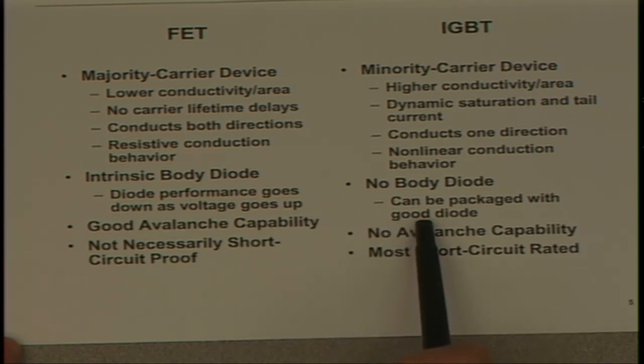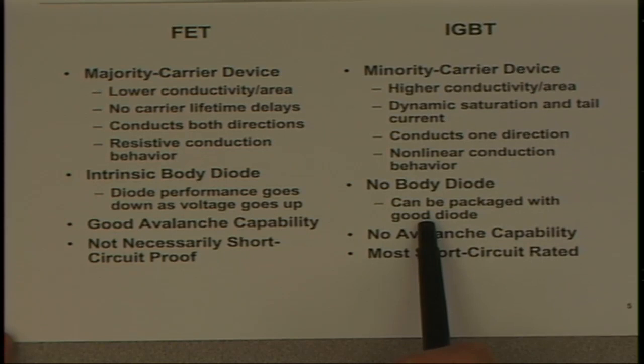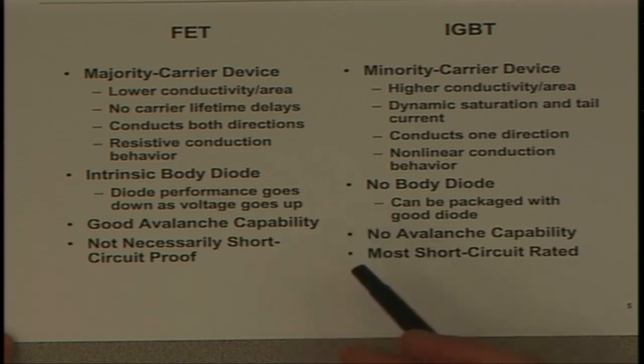However, an IGBT has no body diode, right? So the IGBT die by itself has no reverse conducting. You can make them reverse conducting, and there are companies that offer that. They integrate diodes along with the die, but it's quite a compromise. You typically are better off having a proper diode, because you can use separate processes to make these two different die and optimize them for the application.